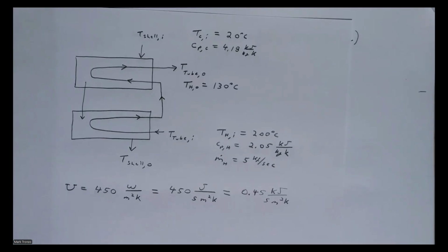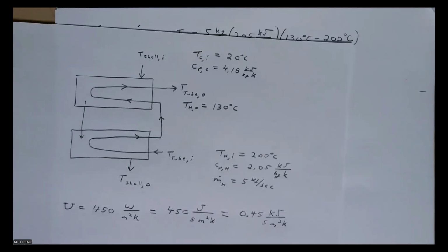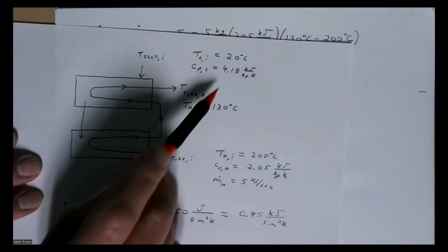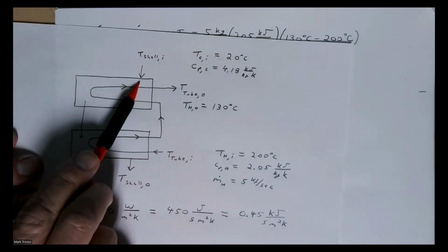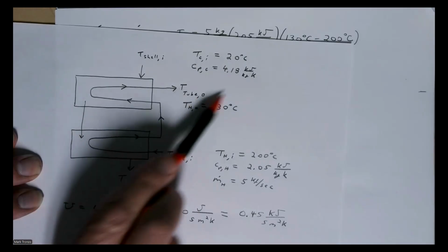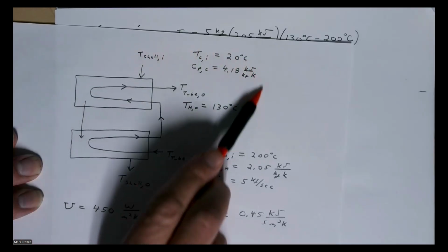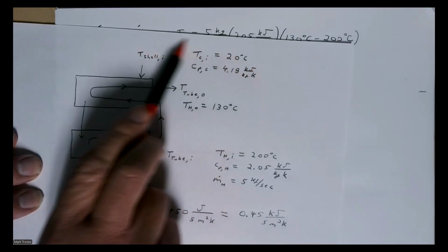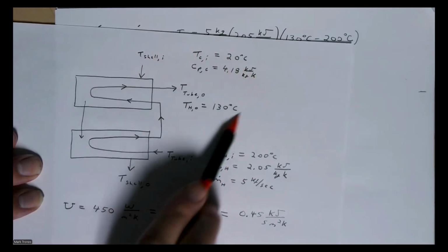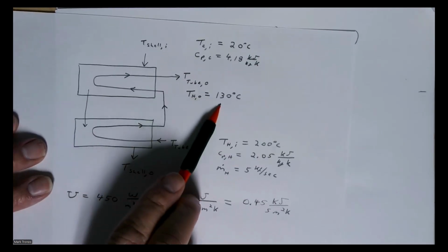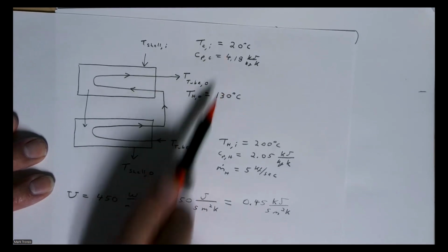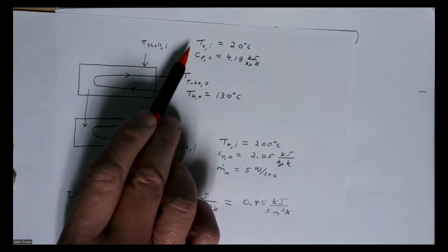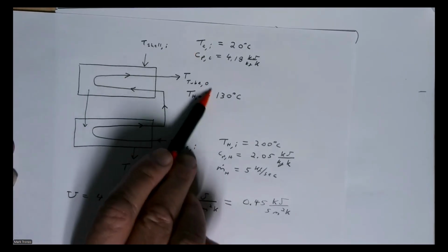And so back up here, we look at, say, in this case, where the cold fluid came in and the hot fluid went out, because this is going to be counterflow. So we look up in this area here and look at this temperature difference. So here we have 130 and 20. And so again, you can call this T1 difference T1 or T2.